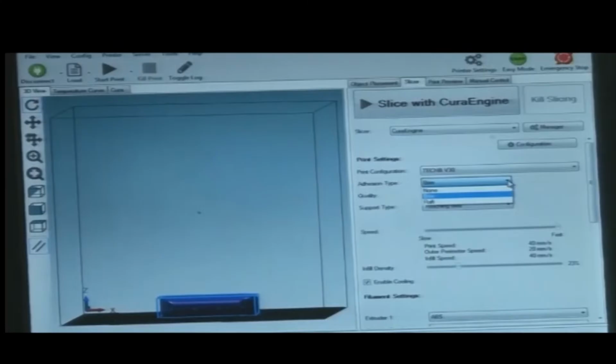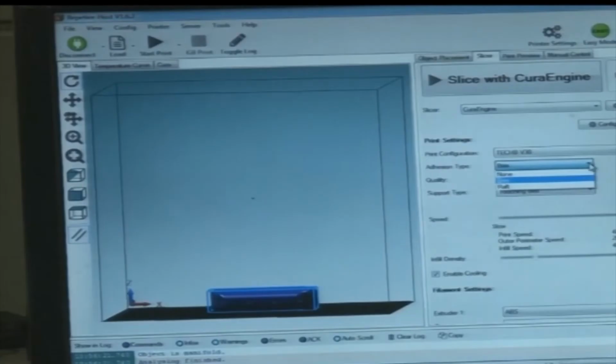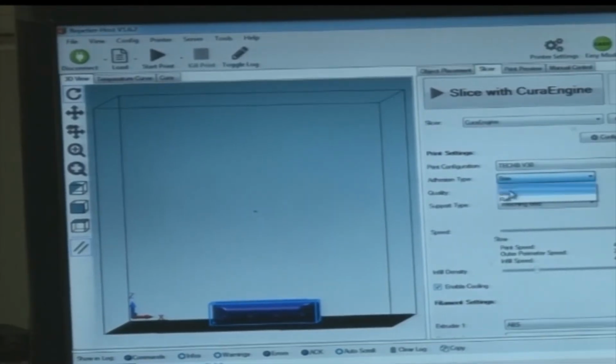It is actually known to the manufacturer whether the quality of the product varies with using brim or not. In general, the brim command is preferred to reduce the wastage of material. The second layer onwards would follow the CAD geometry. In this specific model, the brim and raft are only the first layer, as I mentioned before, but in certain machines the raft can be more than one layer.